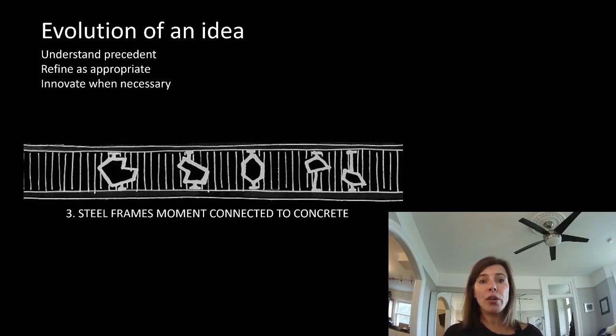Switching from concrete to steel is always a pain. We either needed things cast in to accept these, and I've told you before that things cast in are always the things that are wrong. Like 60% of the time, they're out of place. So this didn't give us a lot of tolerance, and these were somewhat difficult elements. And you can see there were only 2 points of support, so it needed to be held in place until these complex connections could happen.